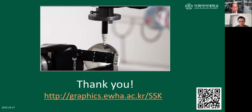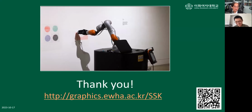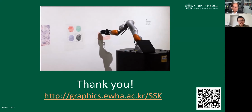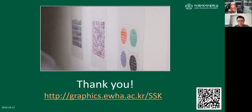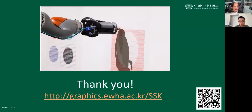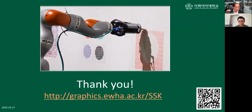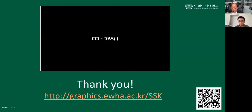Collision detection: if any of you know me, I've worked on collision detection for so many years, but I tried to avoid the collision detection problem in this case. As you saw already, the robot drawing itself takes quite a long time, so if you take into account collision detection, you will incur even more overhead. So instead of detecting collision, we tried to avoid collision. By always approaching from the perpendicular direction to the canvas, we can maximize the possibility of avoiding collision. But of course, it does not guarantee it.